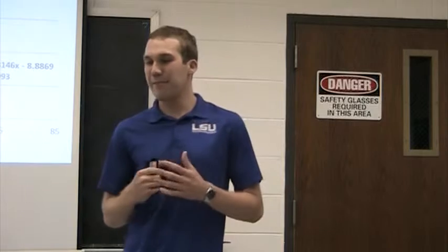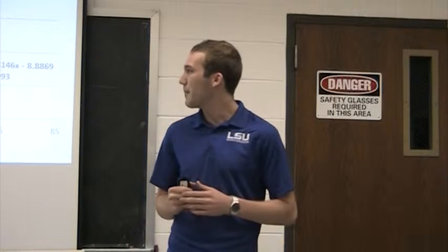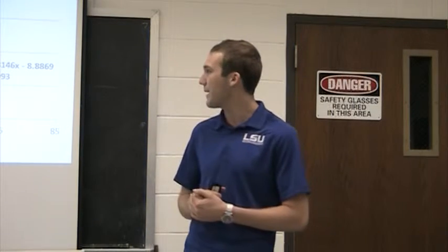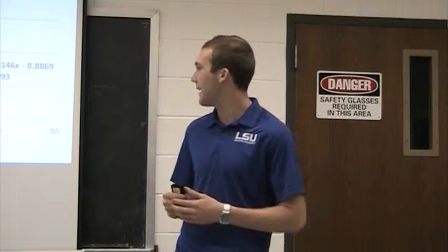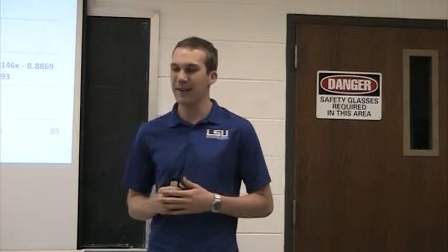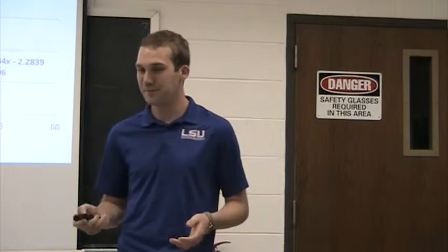So we were asked in the lab manual to calculate or predict some calibration curves. This first one is the fuel flow in gallons per hour versus the RPM of the engine. These data points were given to us in the manual, and I used a quadratic fit, and the correlation coefficient is about 99.3%, which is pretty good.